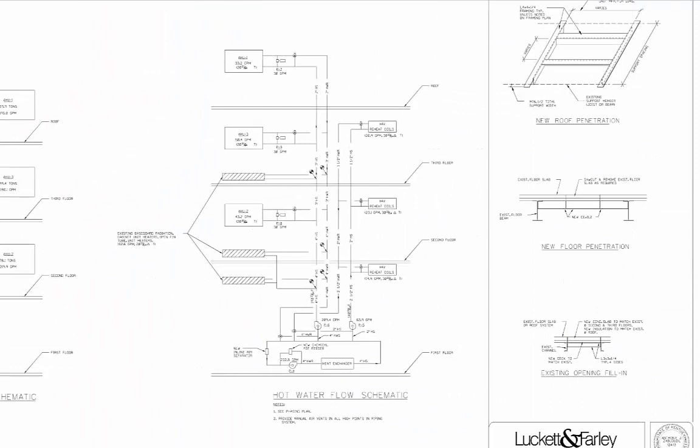There's often a piping schematic for each hydronic system located on another drawing sheet. Such a drawing might be labeled pipe schematics, or those schematics may be found as details on a mechanical schedule sheet or a control sequences sheet. These schematics are not to scale, but they provide a good reference to the installing contractor and for you after construction of how the systems are supposed to be laid out. That is, where in reference to each other are the major components of the system being placed.